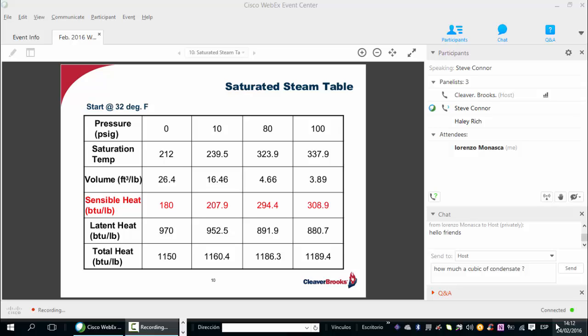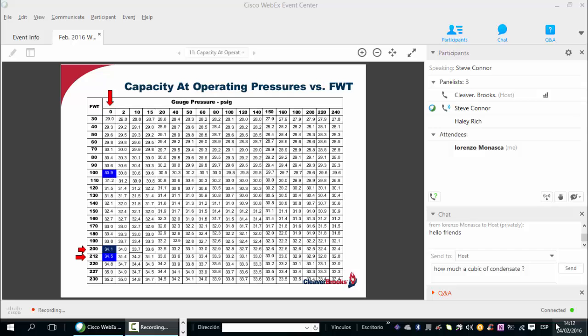The sensible BTUs required to produce a pound of steam at the increasing pressure continues to rise. Remember, this is the liquid form of that pound of steam, and it represents condensate, which could be returned, saving the burner from having to make up those BTUs, that BTU debt, and of course that saves energy. And there's another way to look at it.